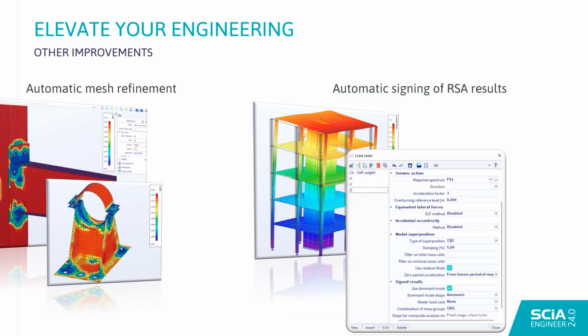Another big improvement also is the automatic signing of RSA results for seismic load cases, a feature that has been requested by many users. Why? Because we have noticed that not assigning the results was the number one mistake that users used to make. Now, this is an automatic process.